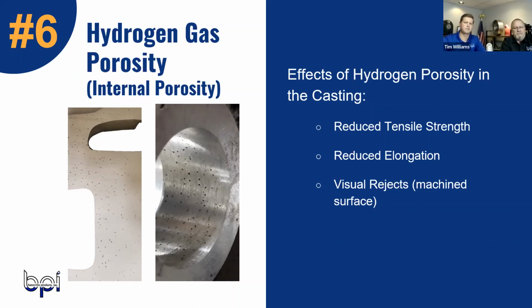So this definitely sounds like something that's very important if a customer is designing a product that needs to be structurally sound. If it's not something you're going to see on the surface, doing a mechanical test or tensile strength test really shows the ultimate internal strength of that casting. You probably won't see it unless you machine it or grind it or something like that and break the surface.